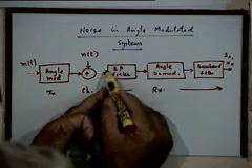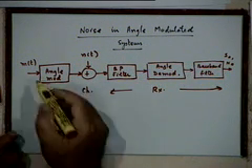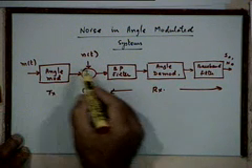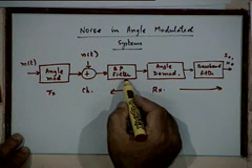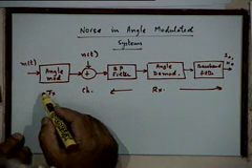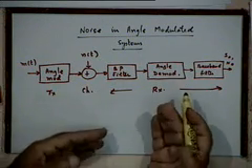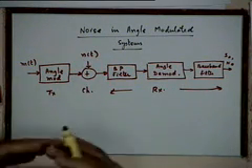So, the bandwidth of this band pass filter is not 2B. If B is the bandwidth of m(t), this is much more than that. It will depend on the peak frequency deviation of your angle modulator, right. That is one difference as compared to the AM signals. It will have some implications which you have to understand.